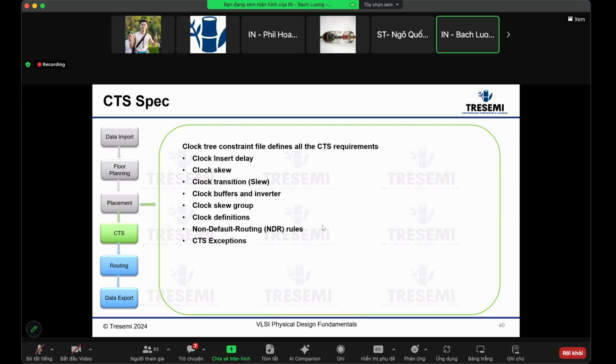Okay, good. Great. So I want to address Ngô Thái on how thicker prevents crosstalk. Actually, thicker will make crosstalk worse because these clocks are aggressors, right? They're very strong. They switch up and down very strongly. So the thicker it is, the more coupling caps it has. It will not help with the crosstalk. It will make it worse. I just want to make sure you understand that it's not helping.